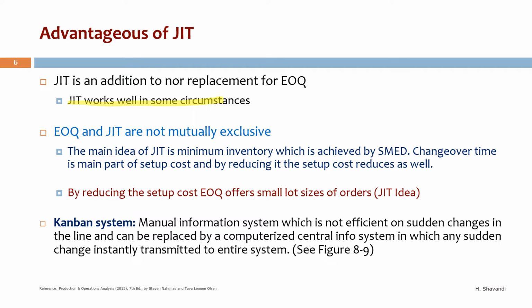We can't implement just-in-time in all circumstances. Just-in-time relies on SMED, which reduces the setup time, the time of changing the dies, very significantly.